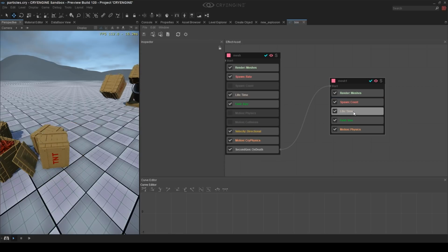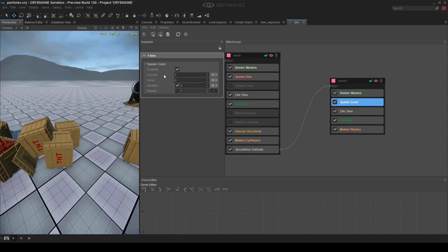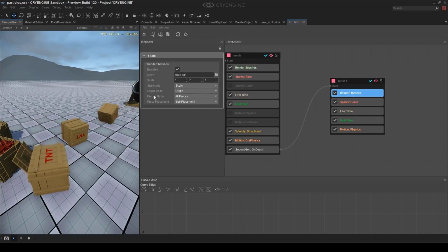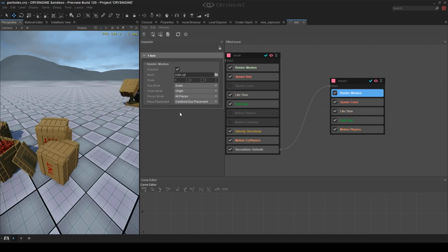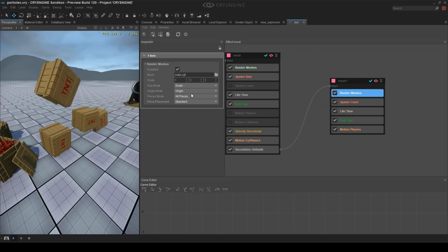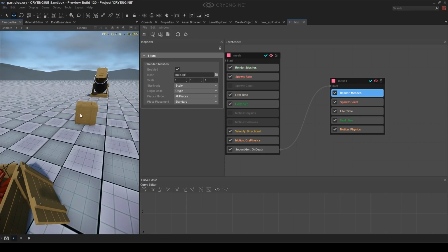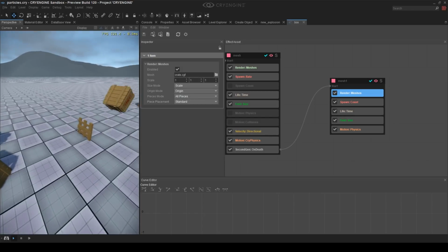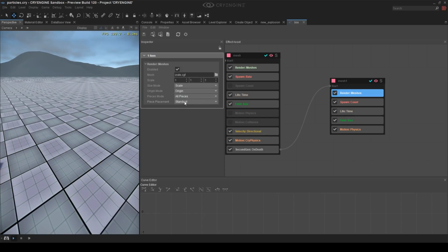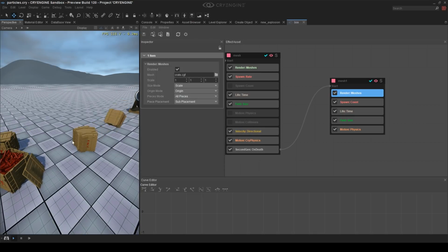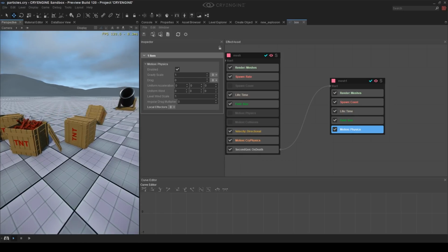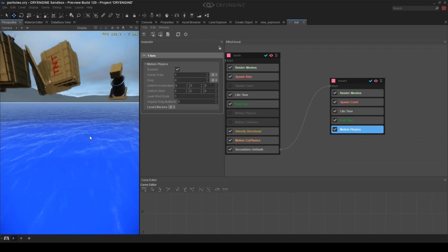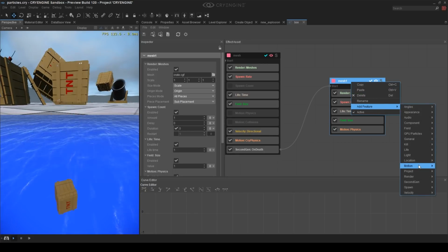So the trick was I need count, not rate, and I only spawn one, but I spawn all pieces in the sub placement. I could center sub placement or like standard. This would give me all the pieces just on the pivot point, which is not what I want. I want the pieces all to be sub-placed like they were in the original mesh. And now I just give them gravity, and they will just collapse because they don't have collision.